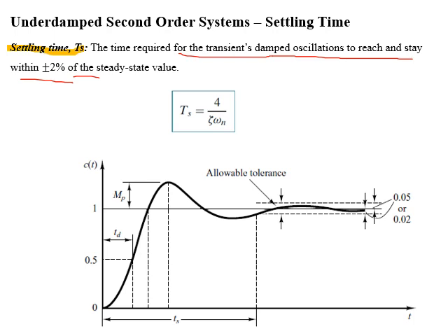So settling time also equals 4 time constants. If you see in the figure, settling time is the time in which the response of the system reaches and stays within the 2% of the final value limit. In some cases, a 5% of the final value limit is also used.